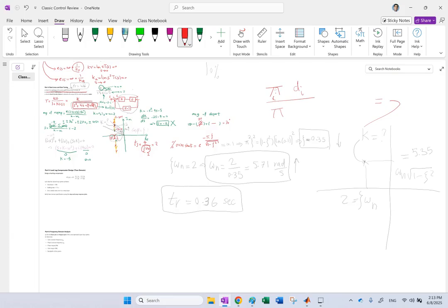So I can call it something else, for instance, Ri. So di's are the distances between the other poles to this one, and the zeros. Now, in this case, you only have these two poles of the original system. There is no zero. So if you find this distance, which you call D1, and this distance, which you can call D2, there is no R, so this whole thing is a 1. So simply, in this case, it is going to be D1 times D2.